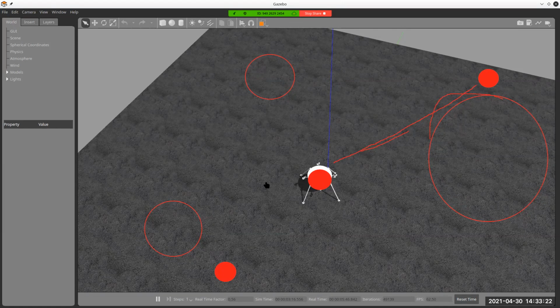So you'll have to be ingesting the altitude. When you see the altitudes beginning to lower relative to the vehicle, that means you're coming up the side of the crater. As an example constraint, we don't want you to get any closer than 4 meters altitude to a crater's edge, so you'll have to respond to that.